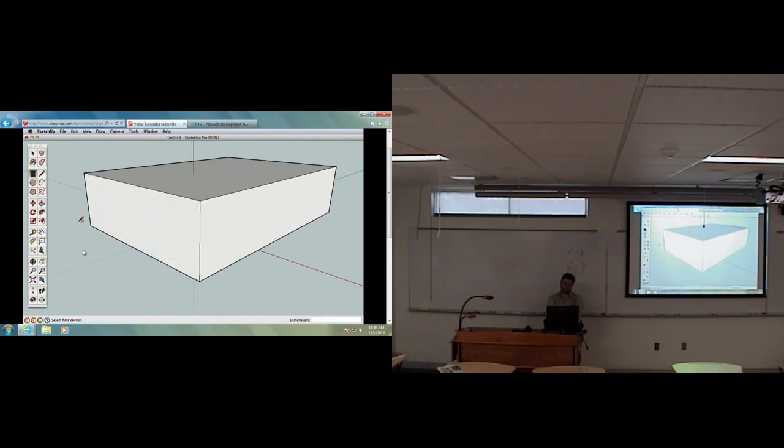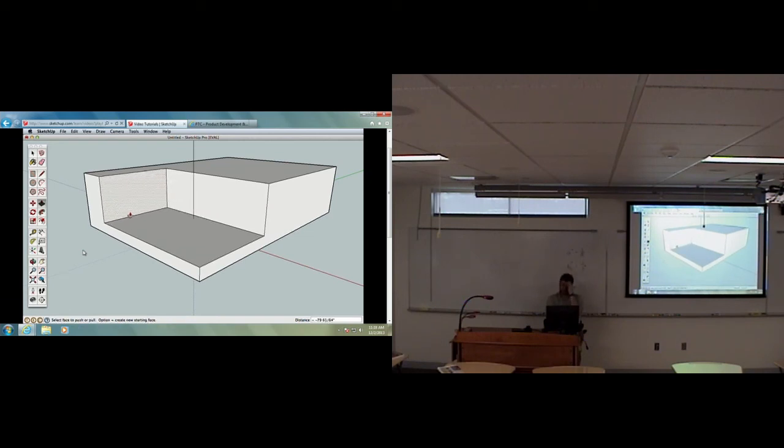Now let's combine more rectangles with the Push Pull tool. Select the rectangle tool and draw a rectangle on our existing box. Watch how SketchUp will give you reference points to help as you draw. For example, to draw from this corner, SketchUp snaps to this point and shows you a green endpoint. Click here to start, pull away, and finish the rectangle. Now use Push-Pull to push this new surface inward.